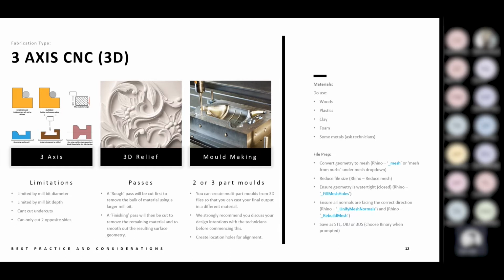And again, you can also cut some materials, some metals as well. So some low-grade aluminiums you can cut, but typically you wouldn't want to go above that unless you've got a dedicated machine for cutting metals, because typically they need to be cooled with water and you have special cutting compounds, etc.